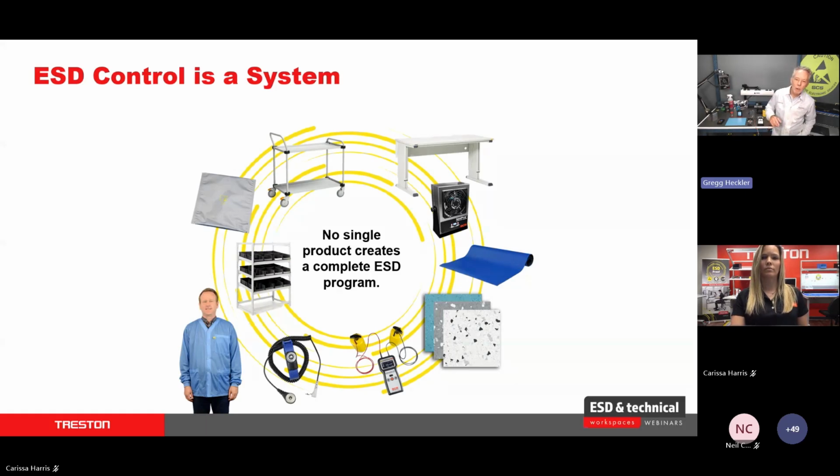Correct. Most of you, I'm sure, are familiar with our industry standard called ANSI ESD S20.20. That standard's made up of multiple components, but it is based on keeping the human body from generating more than 100 volts. That's where the wrist strap comes in, or the ESD footwear, for example. You plug in, I have one over here. We're going to talk about monitors in a minute. But if I have my body grounded through my wrist strap here, I'm not going to generate more than 100 volts. But there's a whole bunch of other aspects.